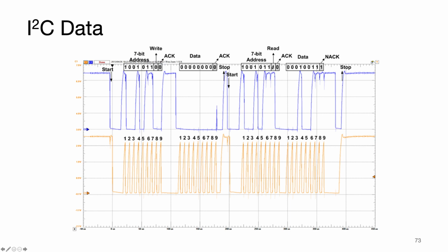Here, so this is the address frame. Now the control frame comes through. Or sorry, the address frame. Here's the data frame. Now this is sent by the peripheral, right? The peripheral is the one that's now in charge. Before, when data was sent out, it was a write. The controller was pushing out all zeros. Now, even though the controller sent the address, the peripheral is taking control of the bus and is pulling this thing up and down, up and down.